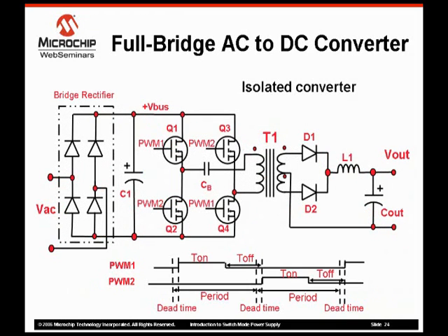Full-bridge AC to DC converters. The full-bridge converter uses 4 transistors that operate in an alternating fashion. 2 transistors on diagonal sides turn on and then off in one PWM cycle, and then the other transistors on the next PWM cycle turn on and off. The flux is reset when the other transistor pair is turned on, so duty cycles from 0 to 1 are possible. There are 2 power pulses transferred each cycle, enabling the use of a smaller inductor and capacitor.